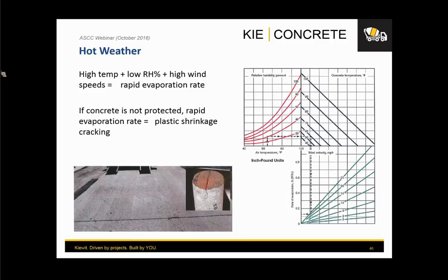But things like that can be avoided if we as contractors implement the right protection. Understand the mix, understand the bleeding characteristics of the mix, understand how the mix performs, what your weather conditions are, if you have a windy placement, if you have a dry day placement, right? Are you going to put any efforts in operations to protect the concrete at early age? Are you allowed to use an evaporation retardant? At what time are you going to come and cure this concrete and make sure that the concrete is protected early, right? Think about those things.